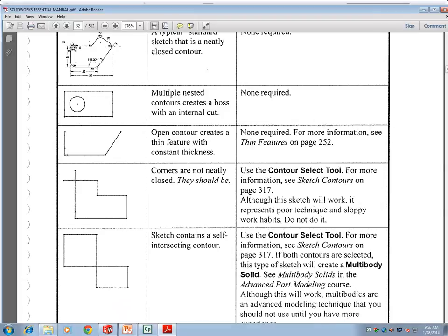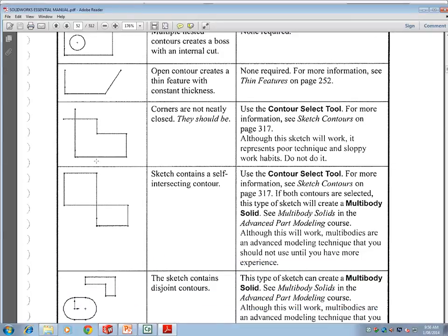And also sometimes your corners are not closed. You'll see that quite often in the initial sketchings, your snap point looks quite close to the intersection, but it will not be. There will be a very small distance. An extra line is added, then you've got to trim that particular line. I'll show you how to trim that line.